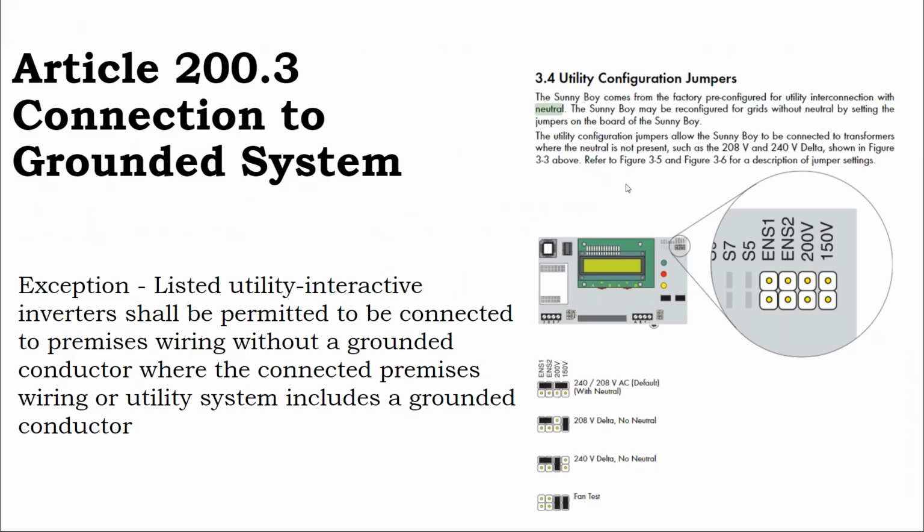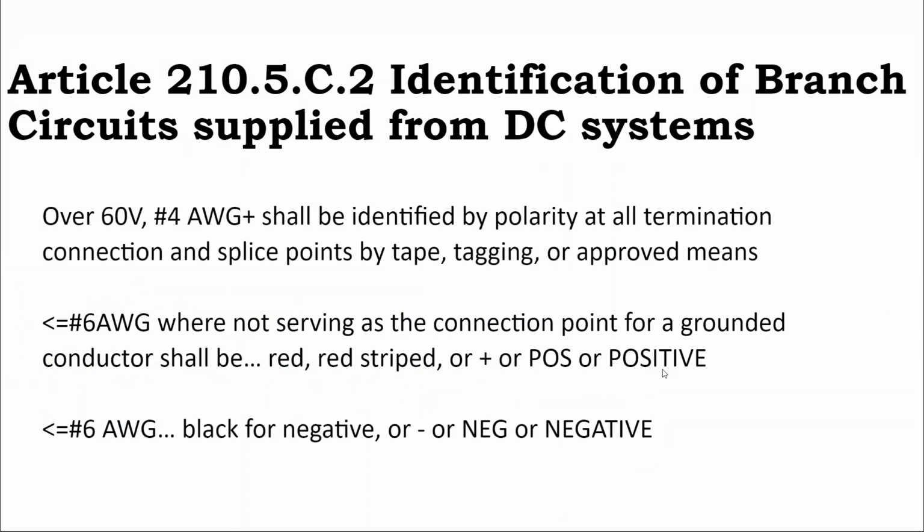And so some inverters will actually have a programmable setting on them where you can say, okay, well, this is 240 volts with a neutral. This is 240 volt without a neutral, and there's other stuff going on there too about matching the electrical load. So some inverters can be configured to work with or without a neutral.